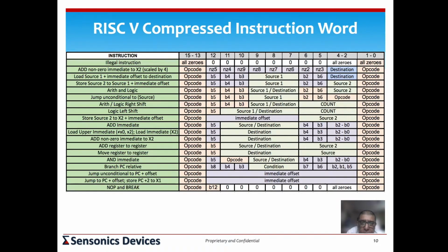So if you have a halt for any reason, if you have a requirement to access the memory for any reason, the processor doesn't halt. It executes the next instruction, depending on how deep an instruction queue you can put in. Those are all choices you can make, and they don't have to depend on your instruction execution engine itself. These are all independent pieces. Of course, the pipeline depth you have to fix. In the design that we are going to do, I fixed the pipeline depth at 3 cycles. But you could put 5 cycles and have a much deeper fetch engine.